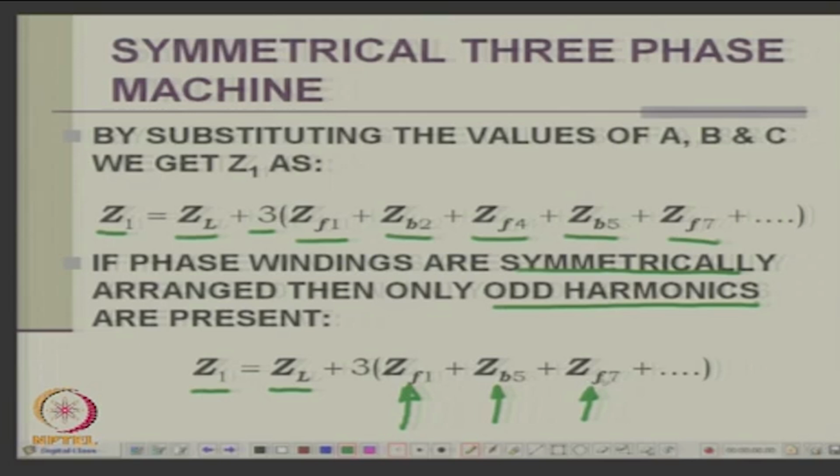So, there will be a forward field which is the 7th harmonic, which means it will be running at 1/7 the synchronous speed. What is this phenomenon called? Crawling. So, if it is a badly designed machine, it will crawl at that speed. So, instead of running at 1500 rpm, it will stop at 1/7. Okay. That is an interesting observation which I got from this theory.